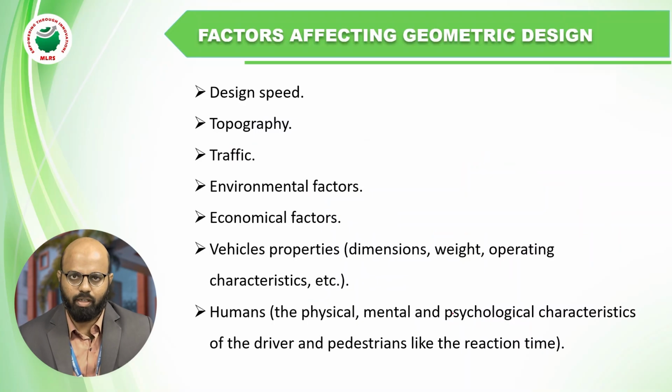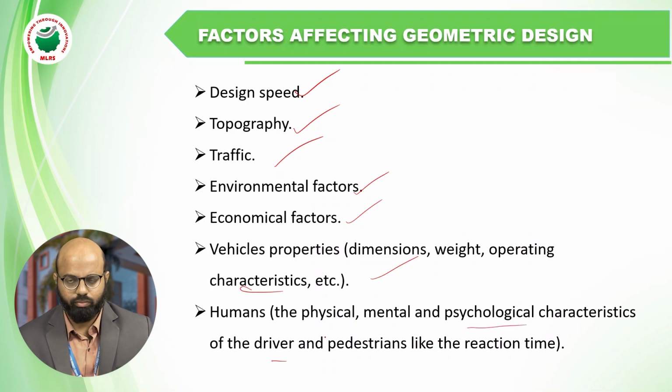What are the factors that affect the geometric design? One is design speed, topography, traffic, environmental factors, economic factors, and vehicle properties. Vehicle features such as dimensions, weight, operating characteristics, etc. And last is human behavior mainly, the physical, mental, and psychological characteristics of the driver.